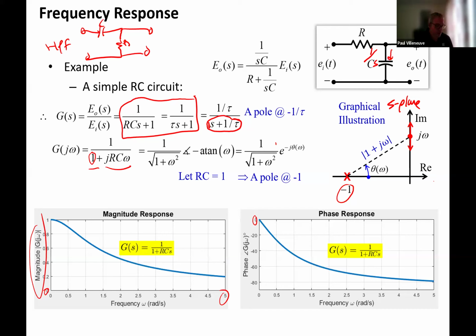However, once we start getting some current there, we're going to get a phase shift between the two. And so our output is going to tend to a negative phase shift. We know over time that this should approach minus 90 degrees. You can see it starts at 0 and works its way down, down, down.